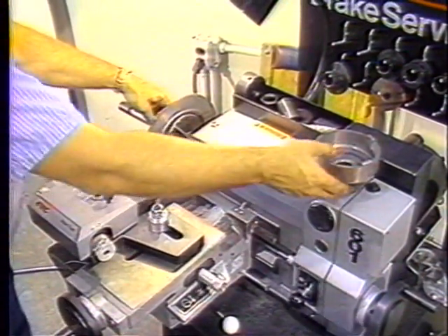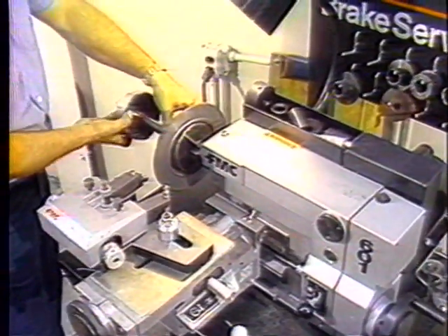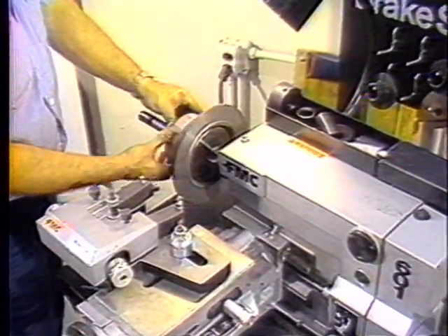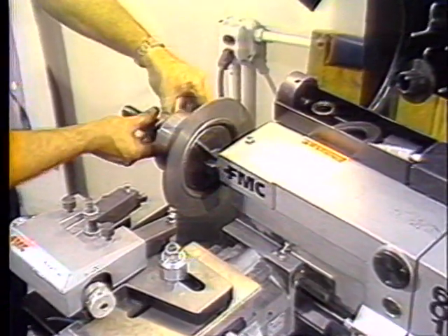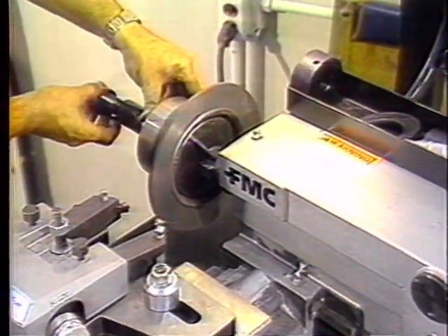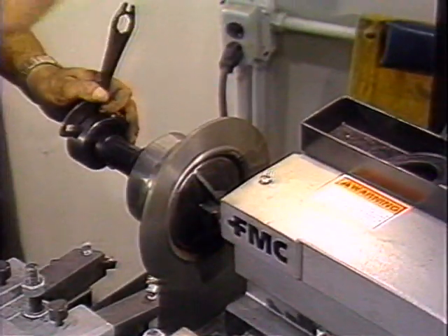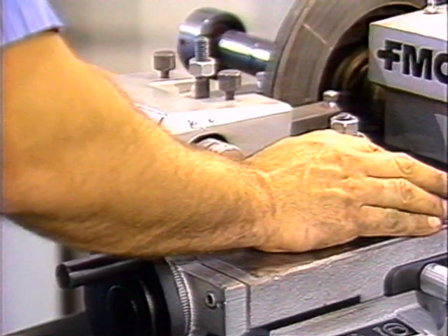Locate and mount a hubless rotor adapter. Mount the centering spring and a cone that fits the center hole of the disc. Mount the other hubless rotor adapter to the outside of the disc. Fill the shaft with spacers as required and place the arbor nut on the end of the shaft.